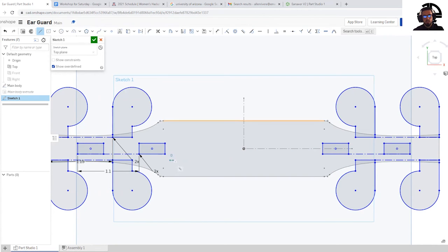Doesn't need to be perfect, but I do want it to maintain that perfect horizontal shape. So we'll create that. Actually, I do want it to be perfect, so I'm only going to stop at the origin. That way it is exactly where we want it to be. Right? So I'm going to stop at the origin, and that way it creates symmetry. And like I said, we can just use the mirror option to create that sense of symmetry, even across this plane as well.